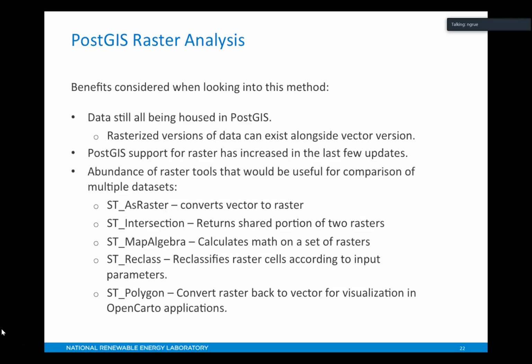By doing the pre-processing up front on the rasters to make sure that they all align correctly and have the same resolution and same ESRI IDs, for example, that gets rid of a lot of overhead. And so it also makes the geometries a lot simpler because you're not having to look at vectors that have all kinds of different vertices and shapes. Everything has the same shape. And so raster will really get rid of a lot of that overhead.